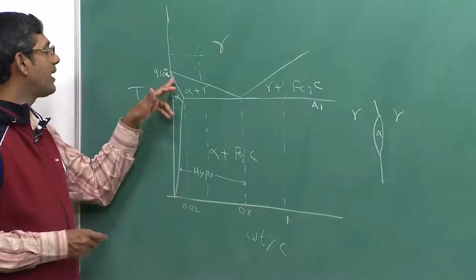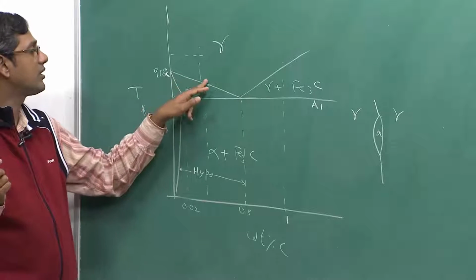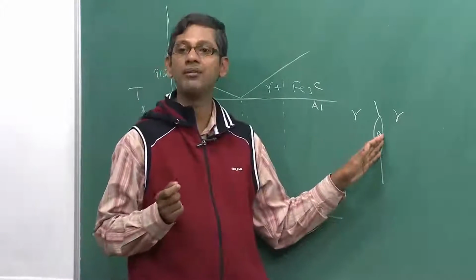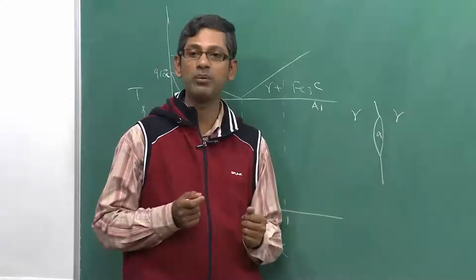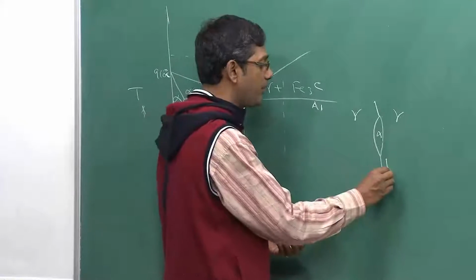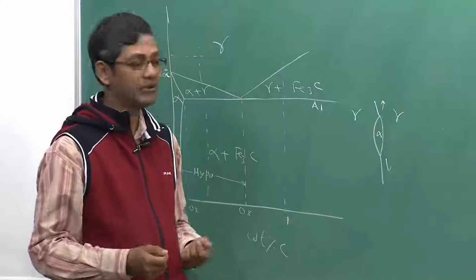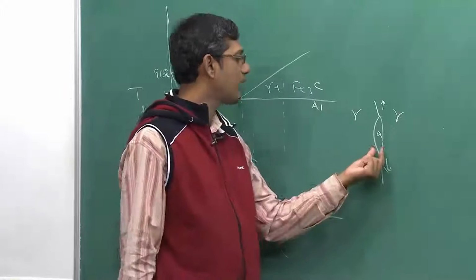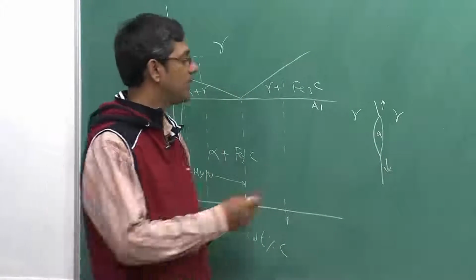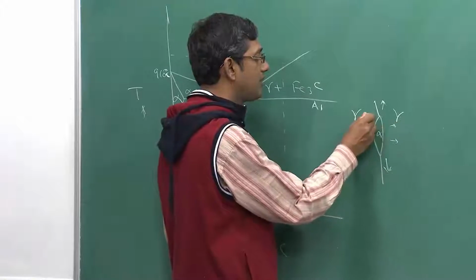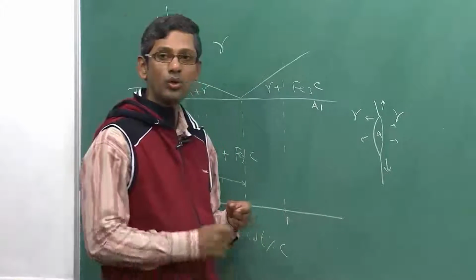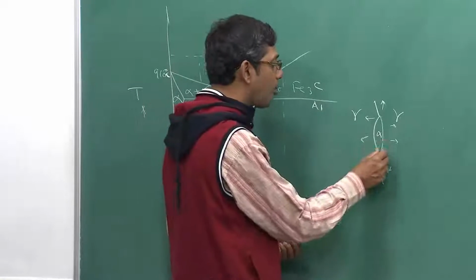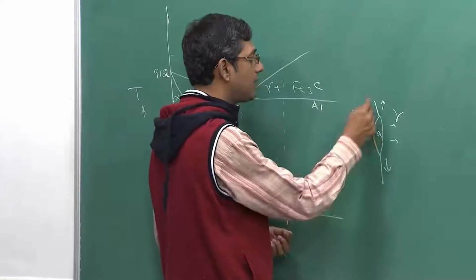As you know, alpha contains a very low amount of carbon, but austenite contains quite a large amount of carbon. So, carbon needs to diffuse out when the alpha grows. That diffusion of carbon can be very fast if alpha forms along the grain boundaries, because grain boundaries are the sinks of carbon or the paths of fast diffusion. As soon as the alpha forms, it rejects carbon into the nearby gamma grains, and therefore the growth of alpha depends on how fast it can reject carbon, and because of that alpha initially grows lengthwise along the grain boundary.